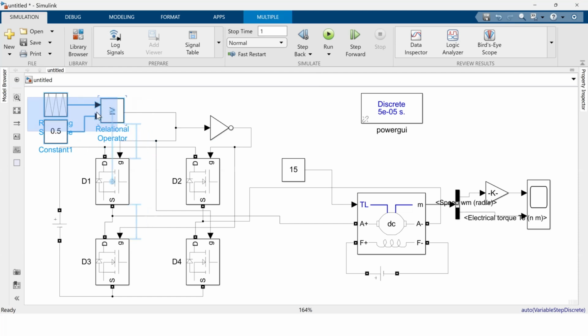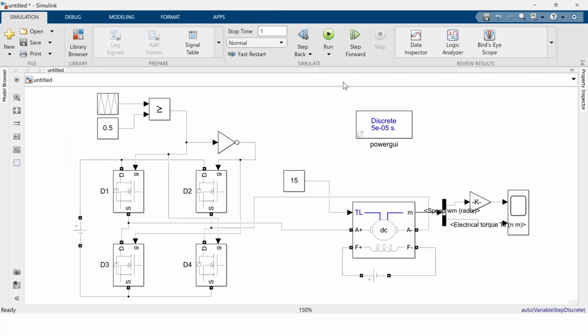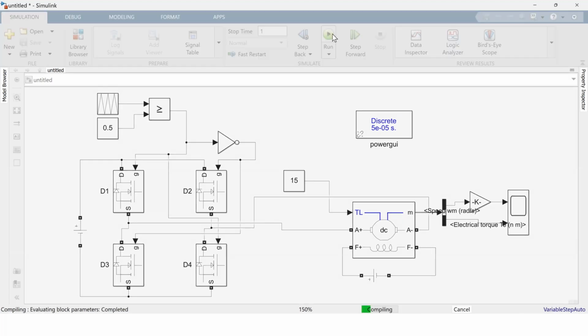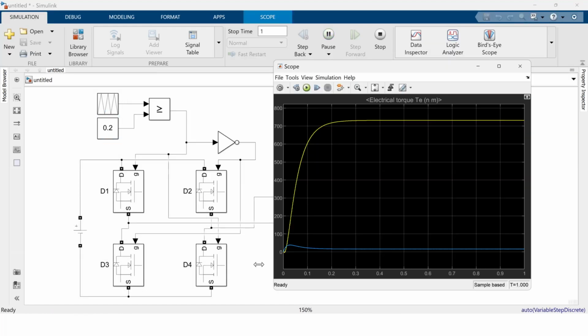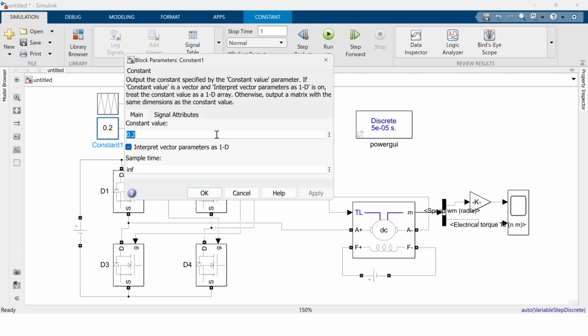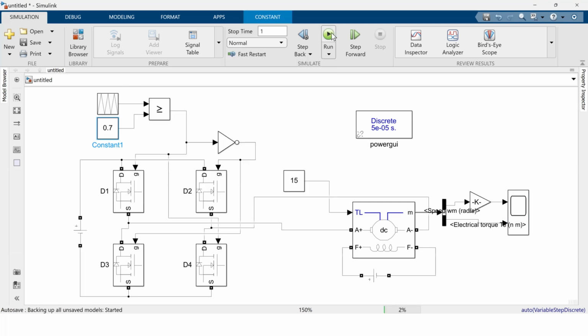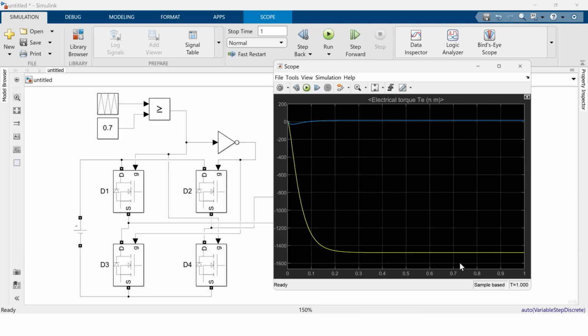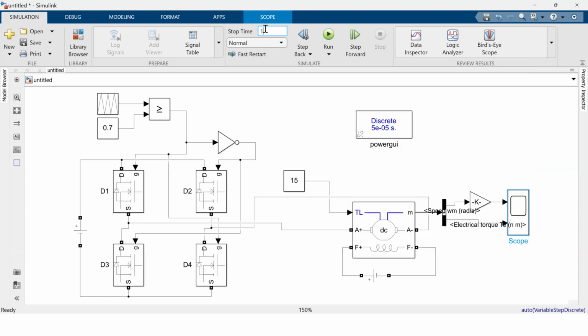Okay, you are following the things. So, simple DC motor control. Now I'm just trying to run this one. Let us keep 0. Yeah, the speed is positive. In the same way, if you go more than 0.7, the speed will be in the reverse direction, right? If you operate continuously, in between we may apply brake mechanisms also. This is a very simple PWM control. Similarly, we can apply a brake mechanism also.